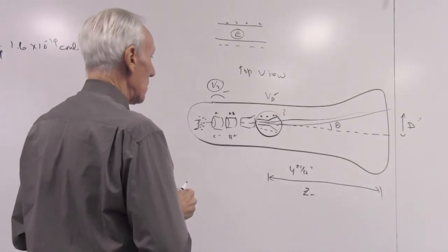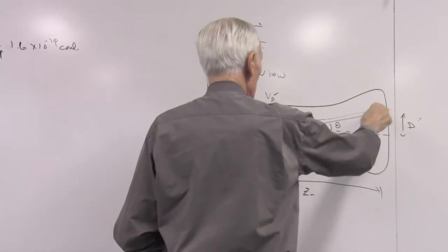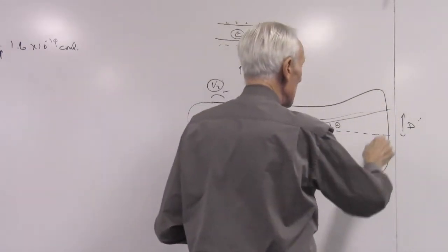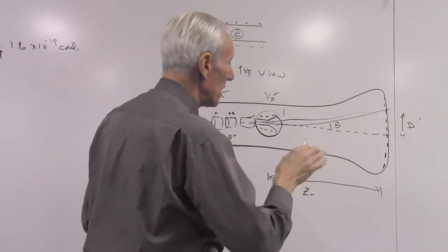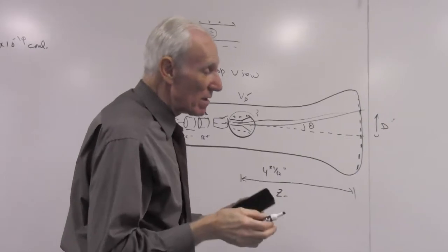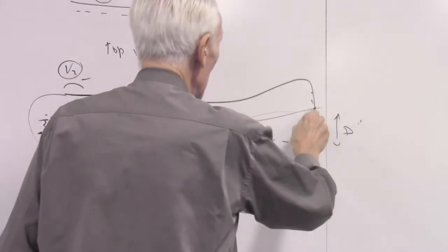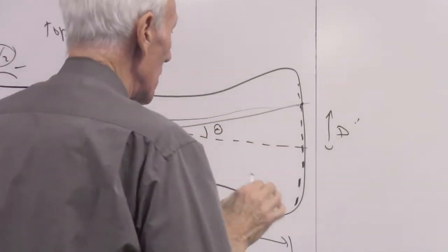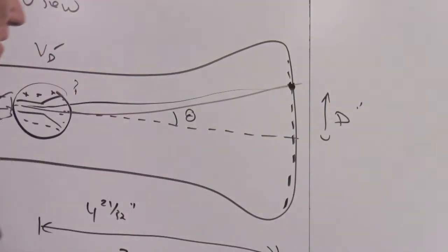Let's just stay practical here. What's the job here? The job is to figure out where these electrons are on the screen. When the electrons get to the screen, there's a phosphor coating on the inside of the screen. If they have enough energy, more than 200 electron volts, then when they hit the screen they're going to light it up with a green phosphor. So there'll be a dot on the screen where the electrons are. And we'll talk more specifically about how to make a nice looking dot with your controls on the power supplies over here.